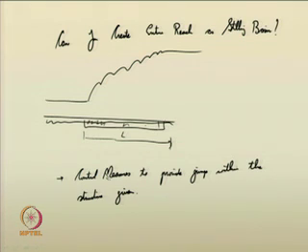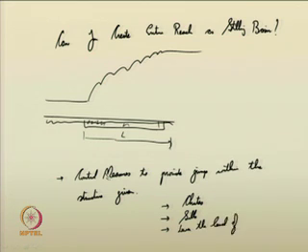You can provide control mechanisms like chutes, sills in the channel bed or near the stilling basin, or you can even lower the level of the stilling basin.